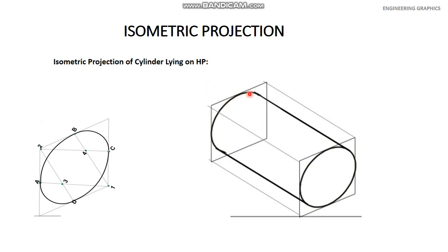So in this square, draw a complete circle with four center method. Now you have two circles, one is here, and join these two circles with two lines, one line this one and one line this one, and remove this portion of the circle because only this circle will be visible to you, and another circle will not be visible to you.